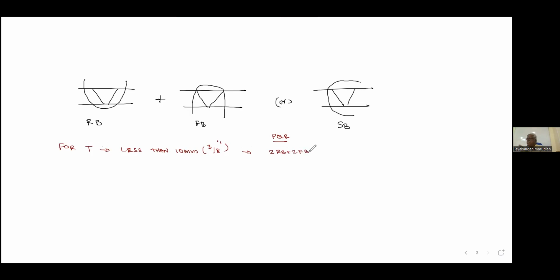No need to remember all these things. This is all open book only. You should know how to refer to it. Suppose you are qualifying a welder, we call it a WPQ. When qualifying a welder in 5G or 6G positions, it is two root bends plus two face bends. Other positions, one root bend plus one face bend.